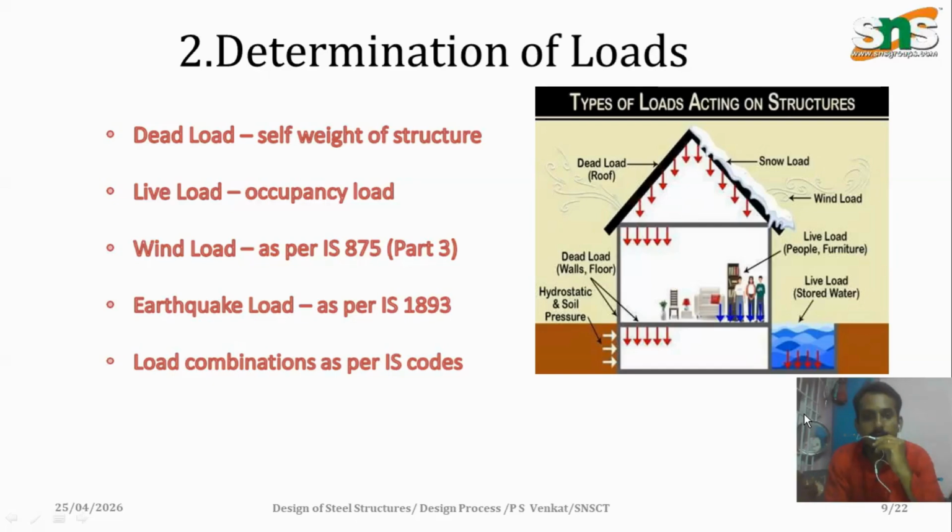Next comes load calculation. We consider different types of loads such as dead load, that is self-weight of the structure, live load, the people, furniture and other moving parts, wind load and earthquake load. This step is critical because a wrong load estimation leads to wrong design.